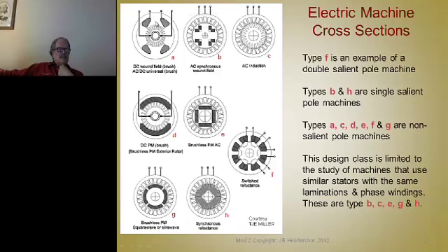The flux that comes from this electromagnet can be adjusted. So if you connect a DC power supply across here, you can vary the strength of this field and vary the whole torque speed curve and characteristics of the machine. But on the permanent magnet machine, you don't have near that flexibility because your magnetic field is fixed. It's not adjustable. You can't make it stronger or weaker.